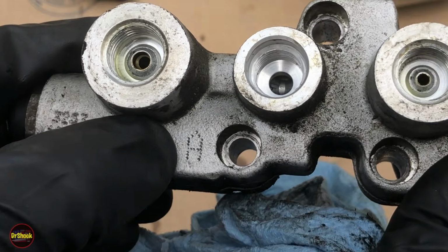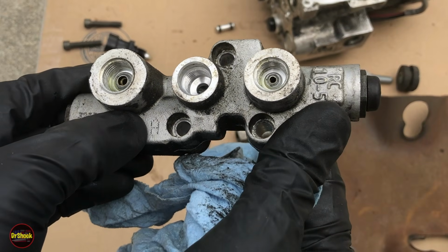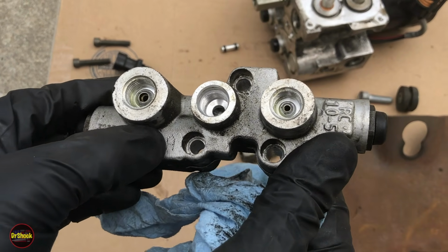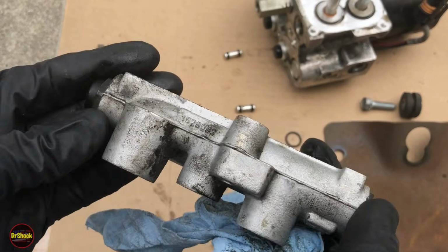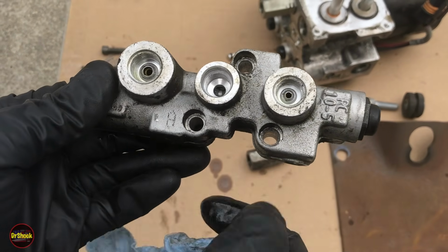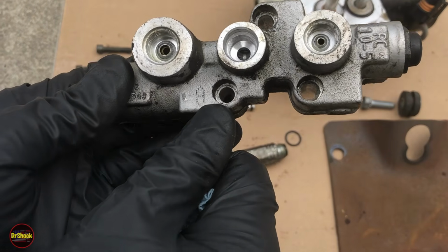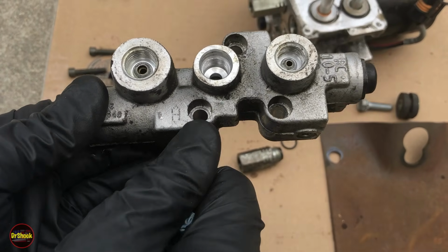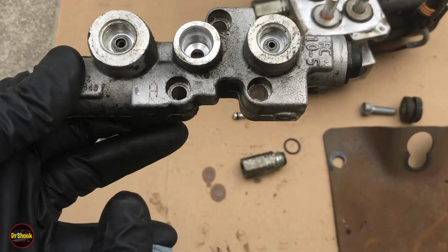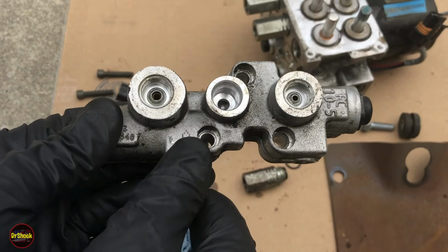You know, for example, an S is very unique. It's only used on a 3/4 ton Suburban. So unless you have a 3/4 ton Suburban, you'll never see an S-coded combination valve. They're not interchangeable. A P van will use an A or an L. A G van will use an A, D, or E. And an S or T truck, like a Jimmy or an S10 Blazer, will use a B or a J.